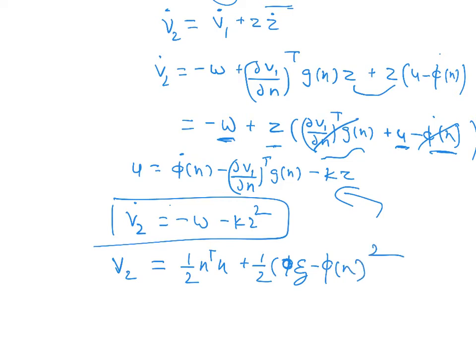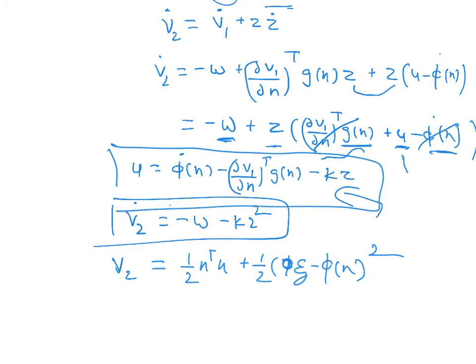You would not have been able to guess this. So you basically build up your Lyapunov candidate function and keep showing at every step that the previous one is negative definite, and at the end when you choose u, the final one becomes negative definite. But this is your controller, as simple as that. And this is the technique, like you have a power now to cancel out. And if things were not known, like g eta was not known, you would have used the same sliding mode approach to make it negative definite. Okay, good.